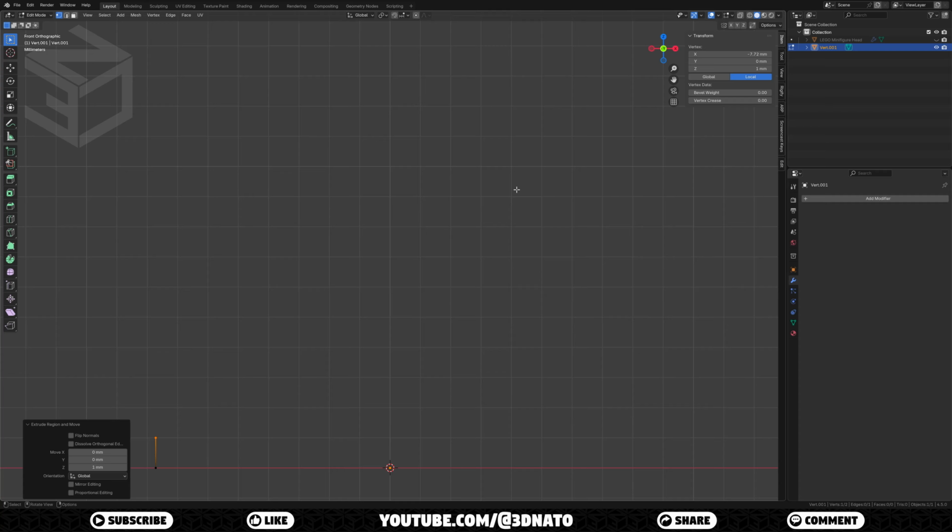As the next segment has an angle, let's set the 3D cursor position. With the vertex selected, press Shift+S to snap, and select Cursor to selected. This will place the 3D cursor at this vertex location and will help us rotate the next edge. But before that, we need to set the transform pivot point to 3D cursor.